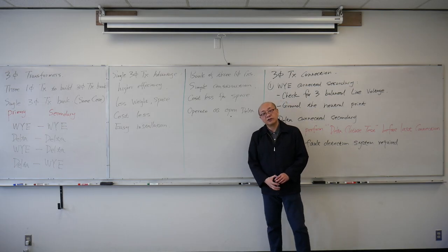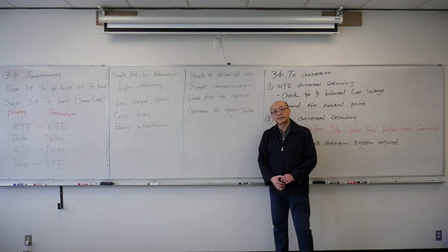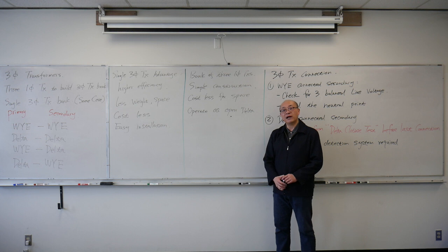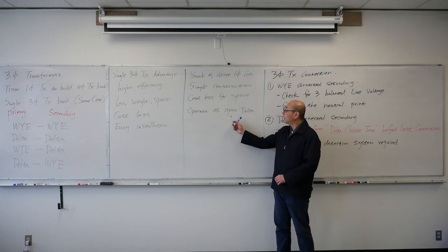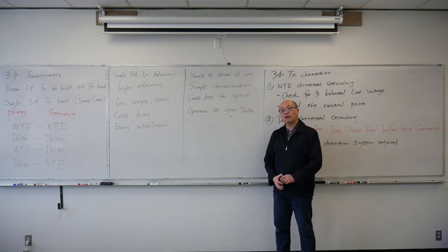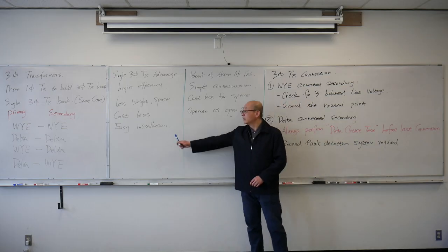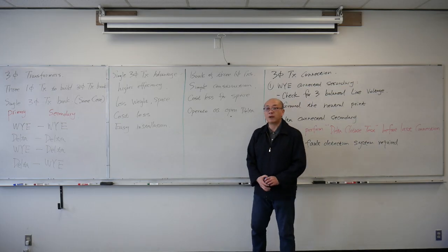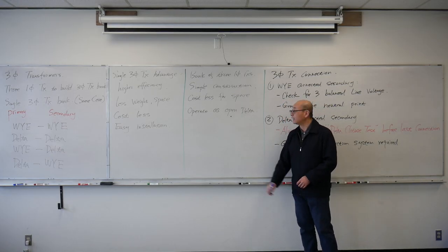Another major advantage of three single-phase transformers is that even if one of the transformers breaks down, I could still connect the last two good ones as an open delta transformer bank. As long as I reduce the load on that bank, it will still supply three-phase power to the load. That's the advantage here. For a single three-phase transformer bank, if it breaks down, you have to replace the whole thing. You can't operate it as open delta.